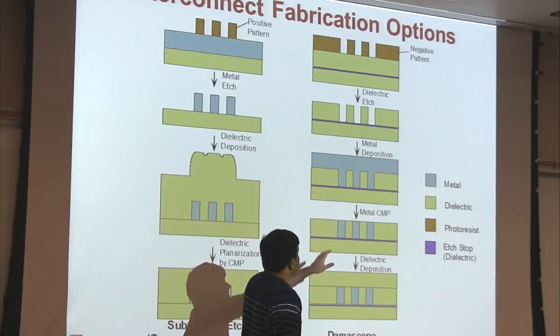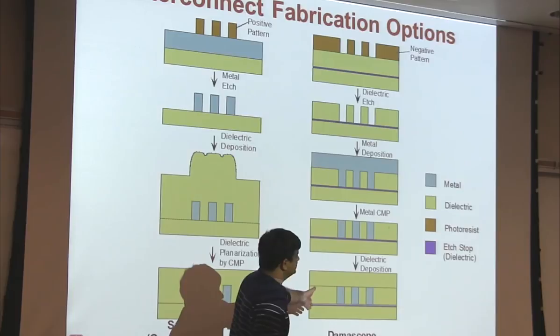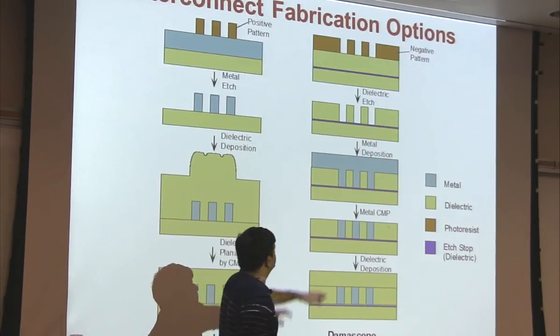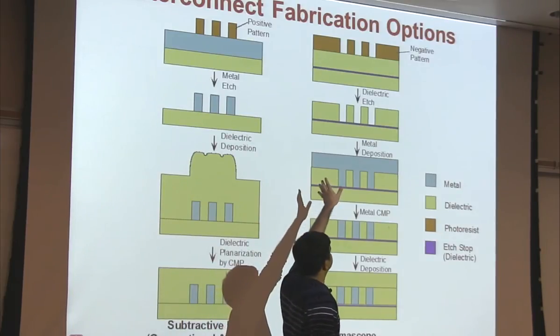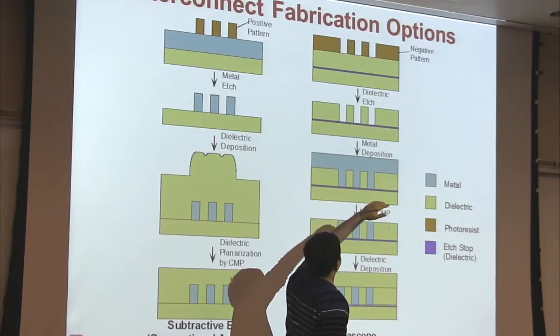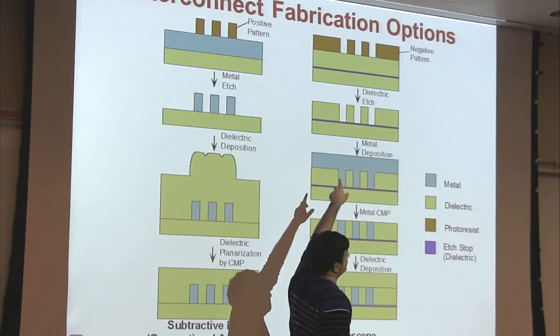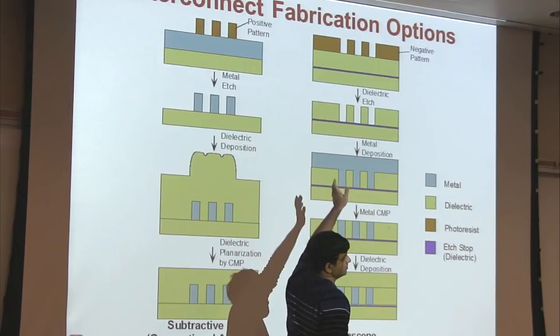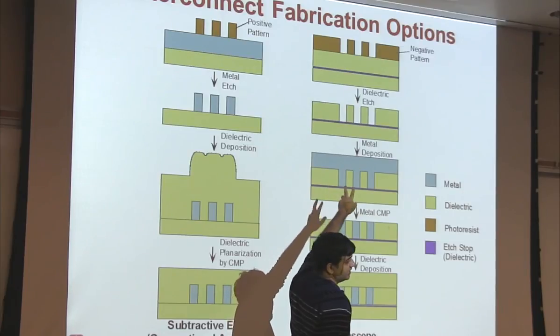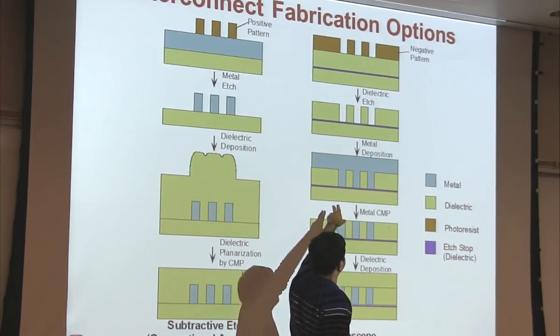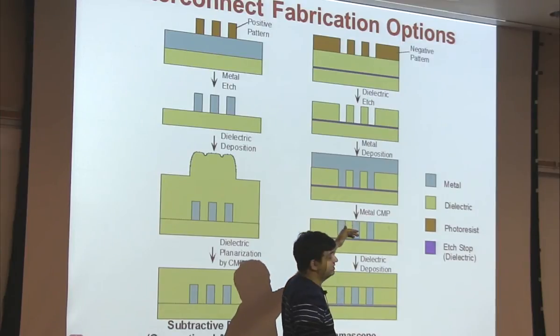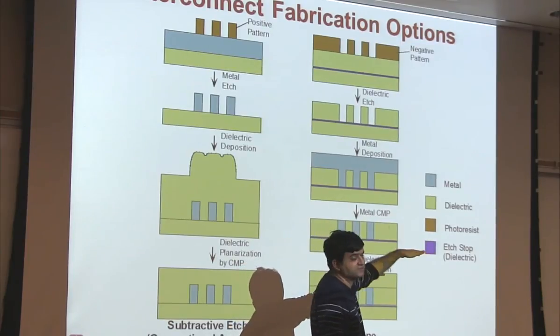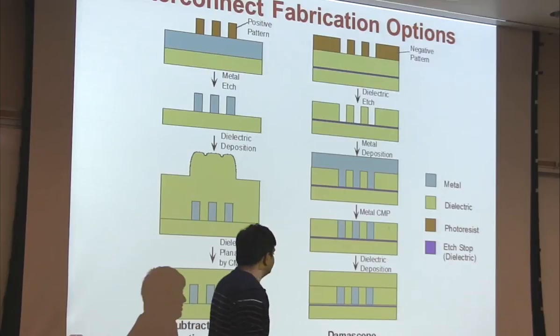Similarly with all the other newer materials that people are using, even in their metal gate, they don't know how to etch them. So the other way to achieve that same pattern is you make a stencil. You start with an oxide and you have that etched top layer, which is that blue layer. It could be a nitride, could be another dielectric, and you etch that stencil into this dielectric, and then you fill it with a material and then you polish it off. And then you essentially have that same pattern again.